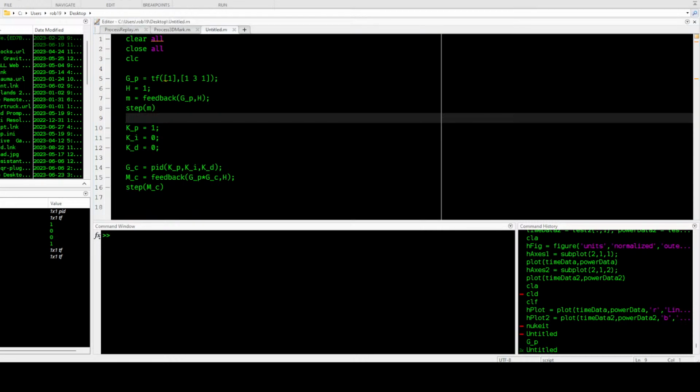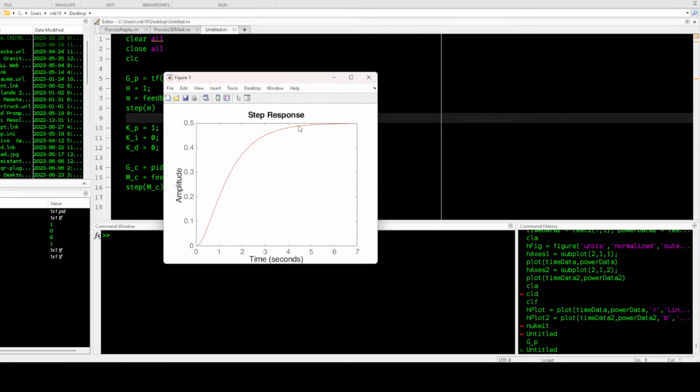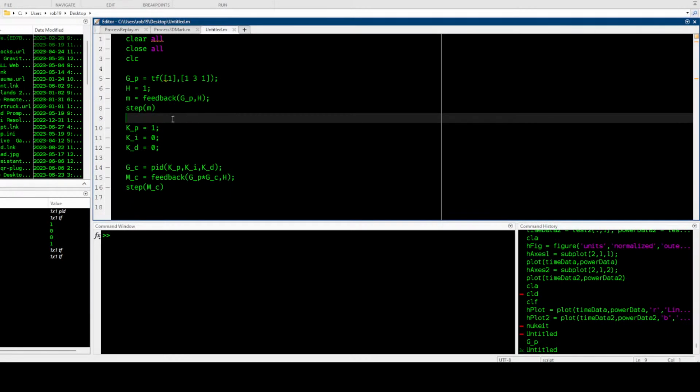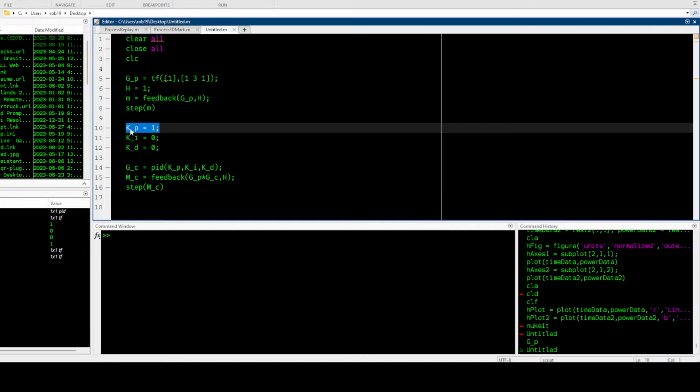Okay, yeah, so proportional gain, this makes sense, did nothing. We said a proportional gain of 1, so the system did not respond. It was responding to the error the same amount as the original one was. Does that make sense? There's a blue curve and a red curve here, and they're overlapping, and they're the same. That makes sense.